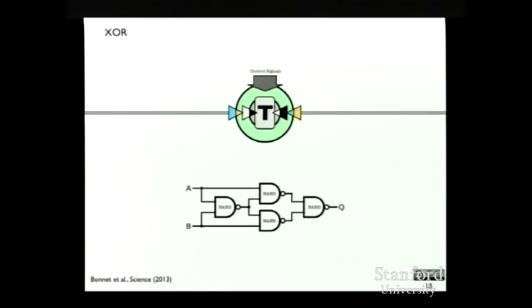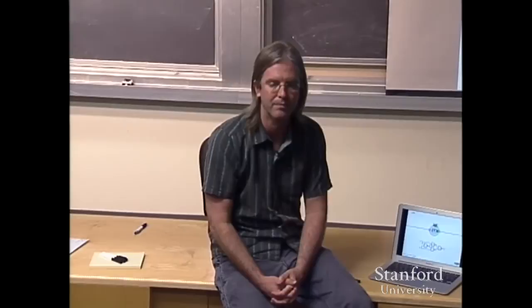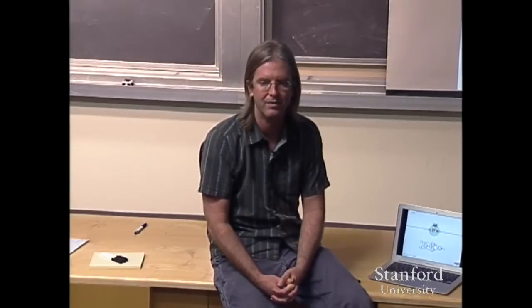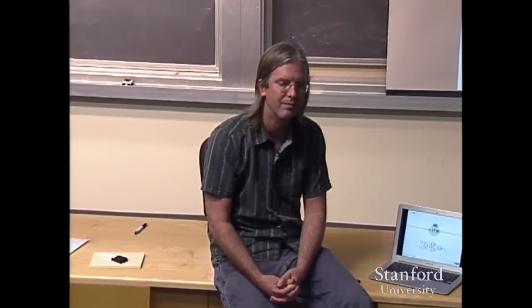If you want input from electrical engineers, the transistor analogy isn't so strong. And you slip into actually calling it a transistor when you initially introduce it as a transcriptor. There's gain there, and it's not a binary thing. And you show bipolar NPN transistors, and they don't work the way you described. I mean, there's a loose analogy, but I'm worried about people starting to actually take it literally.